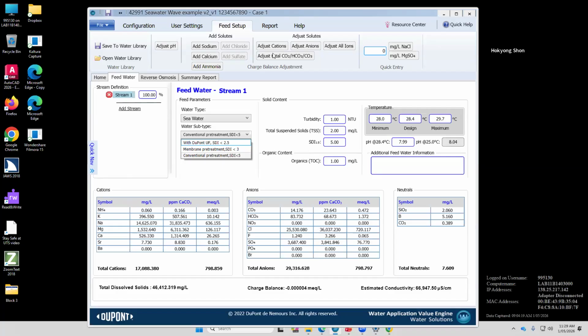And put in a TDS, and they automatically calculate the osmotic pressure, but it does not show the concentration of sodium. They only calculate TDS. So in your report, you cannot see sodium, ammonia, manganese. If you don't put the value there, you cannot see anything. Only you can see TDS, 35,000 milligram per liter, permeate 100 milligram per liter. It's only this rough data you will get.